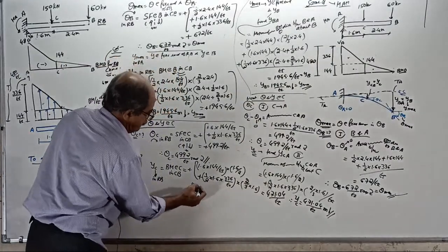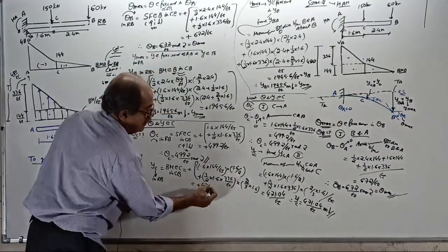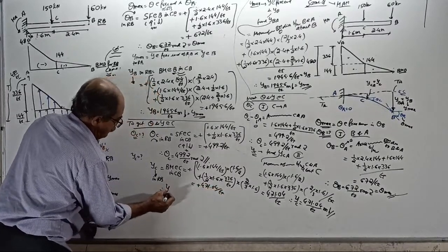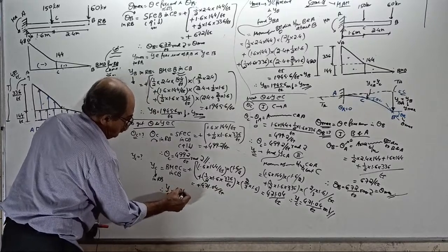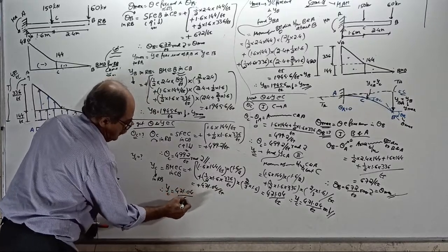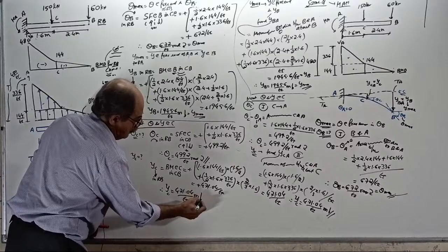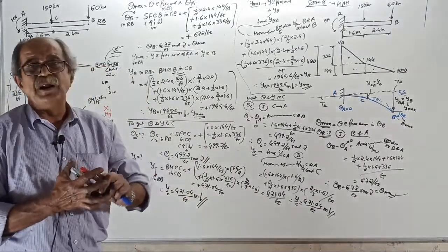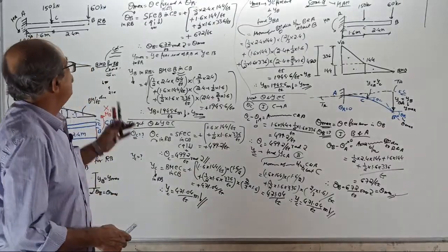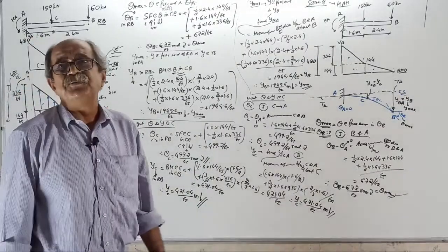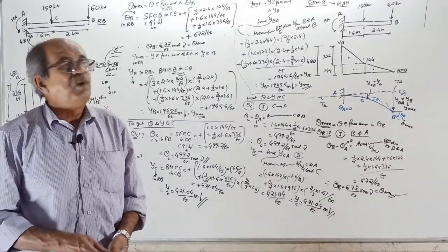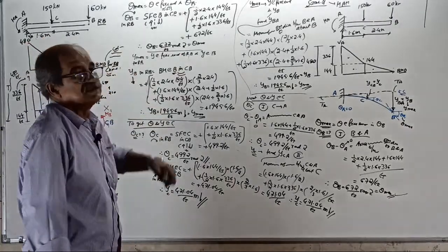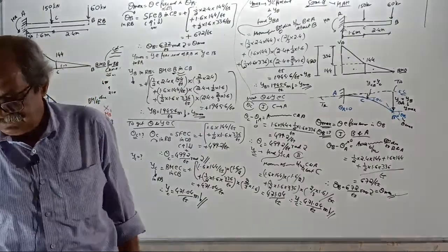Exactly the same. Plus 471.04 by EI. Therefore, deflection at C equals 471.04 by EI meter downward. That is the answer. Tell me, a cantilever beam, left side fixed and right side free, both by the moment area and conjugate beam methods. These two questions are 100% clear.